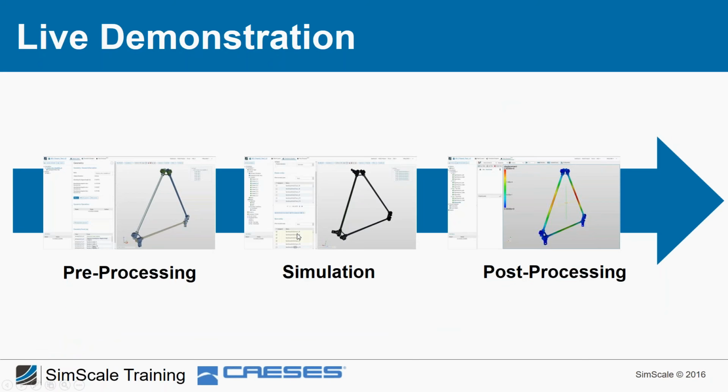And right now what we will do is open a project which contains the CAD model of the subassembly of the frame. We will first of all create the mesh like last time. So we will divide the volume of this body into smaller subvolumes, which are later on used to calculate in these cells stress, displacement, etc. Or in our case, not in the cells, but at the nodes.